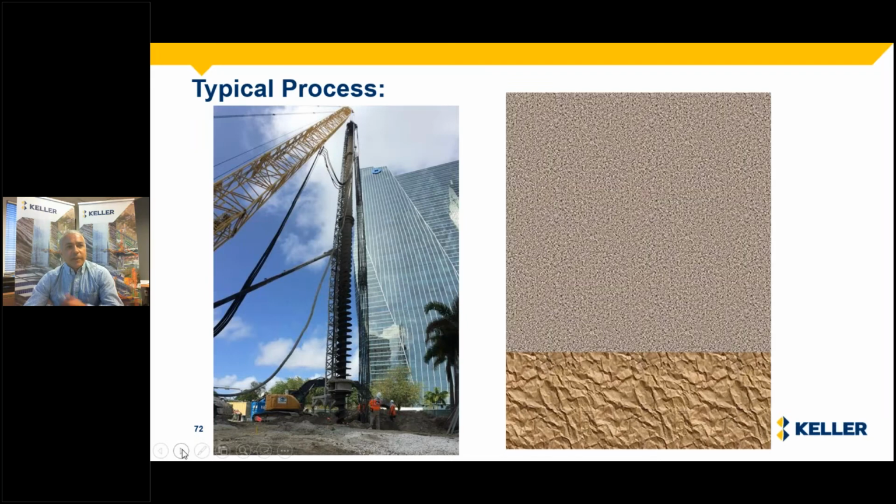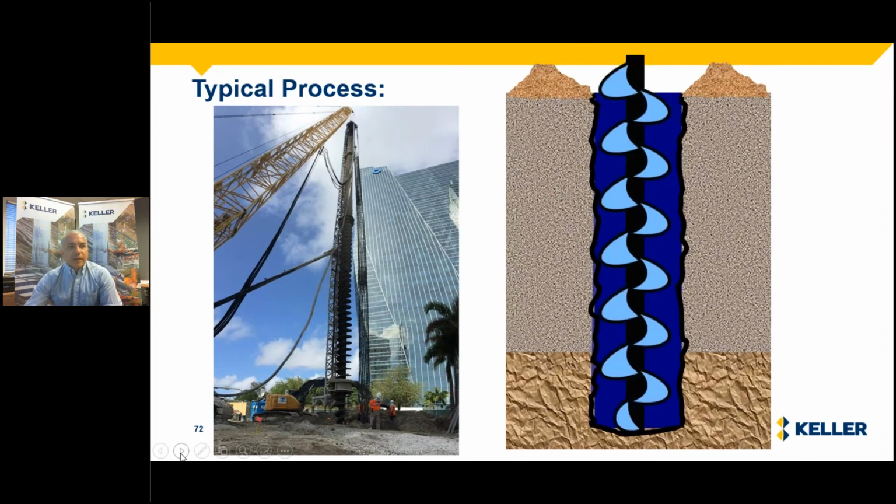With that, you can see there are different lengths and sizes of piles that have been used, but in general terms, an auger is installed in the ground, no casing, going through different soils, clay, silts, sands, cohesive or cohesionless. The drilling will take the spoils out of the hole excavation. The hole will not be perfect. It will have rugosity to it, and then we go into the bearing stratum.